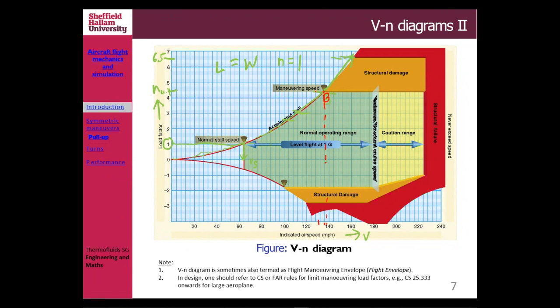So if you go at a lower speed, to the left, for example, the structure cannot be overstressed, and your aircraft will stall before reaching the limit load factor. So between this speed and that speed, you have that limit over there.